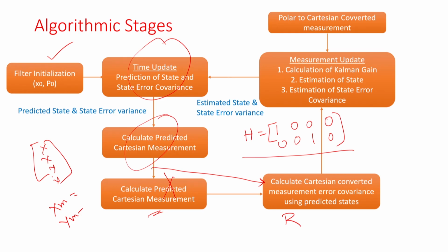Pseudo measurement is not possible all the time. For radar tracking, yes, it is possible to some extent. For UIR tracking also, there is a way to calculate your x and y. But normally, for any kind of nonlinear process, it is difficult to estimate this pseudo measurement, because getting a linear function is sometimes difficult. But fortunately, since we are only concentrating on target tracking, our Kalman filter is only related to target tracking. In our application, it is easier.